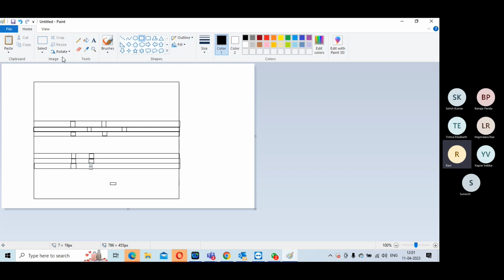We'll talk about spare cell placement. But spare cells are nothing but your standard cells, except their inputs and outputs are not connected. That's all. They are left floating. How you handle each one is a separate thing.